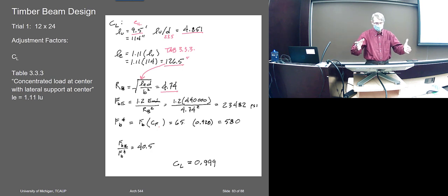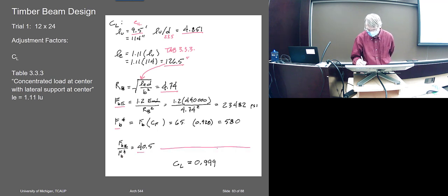This is a foot wide. So calculate the Euler stress, and then run through that big equation. There's the other stress, there's the ratio, and I didn't write the equation, but there's the big CL equation. What number is it? 336.